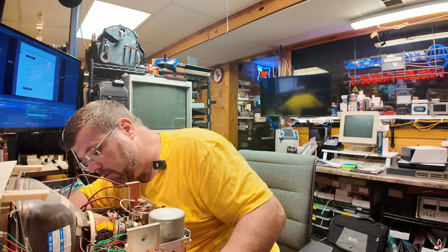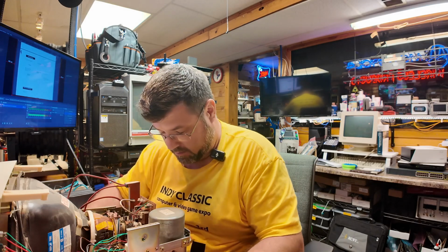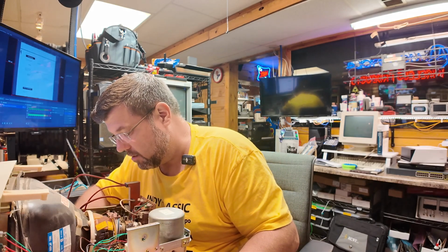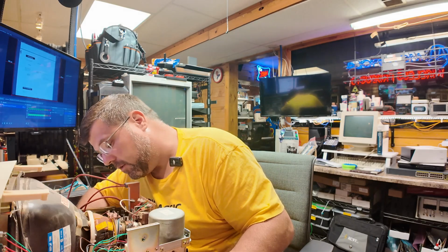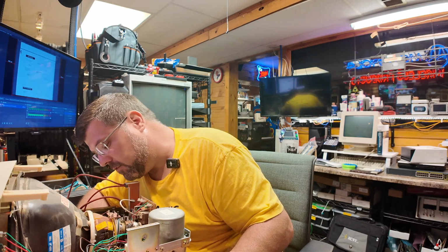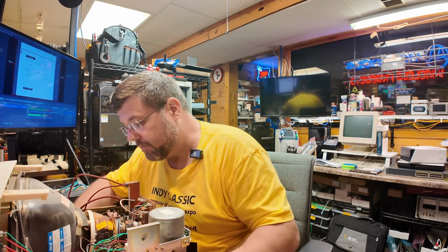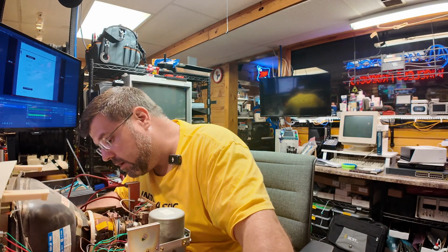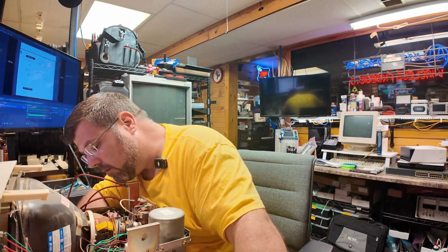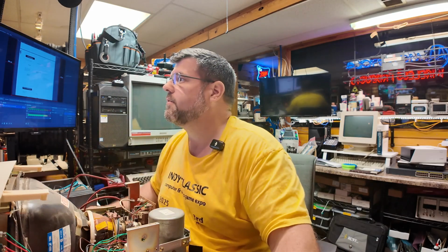Some capacitors up here. Incidentally, I kind of looked at all the caps on this board. I don't see anything swollen, so early 80s caps are really pretty reliable. They don't always go for those first. I'd be more willing to believe that this chip is kapooped. So, IC301. I do not see an IC301 silkscreen. Wait. There it is. Yep, that's IC301.